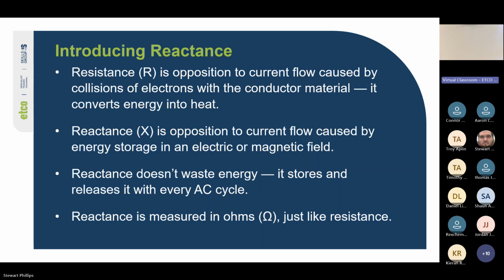So whenever we have a piece of equipment that has inductors or capacitors inside of it, it is going to have reactance. But again, it's not a waste of energy. It is storing and releasing with every AC cycle. It's just not always in a helpful direction.